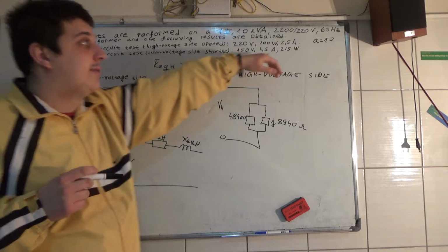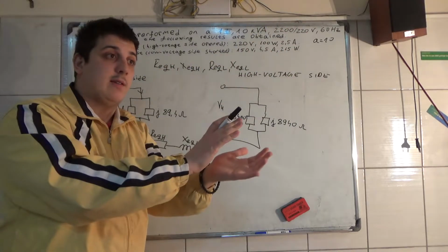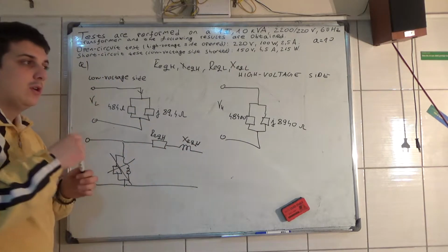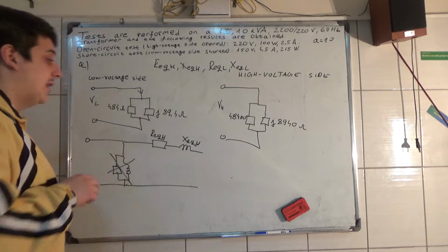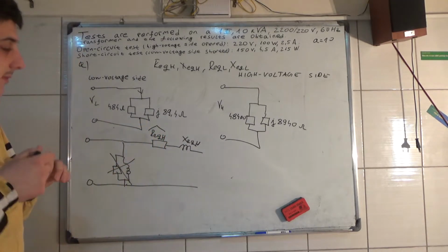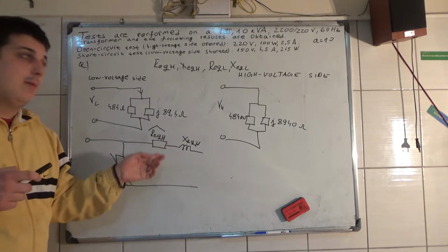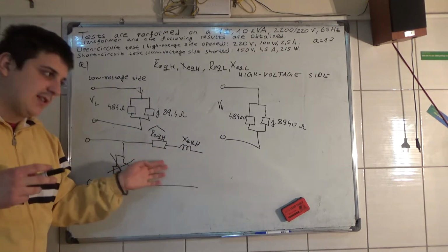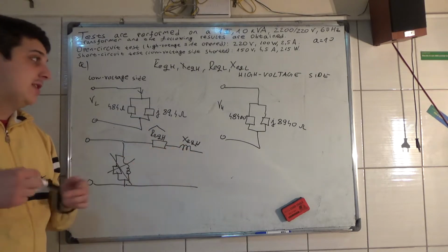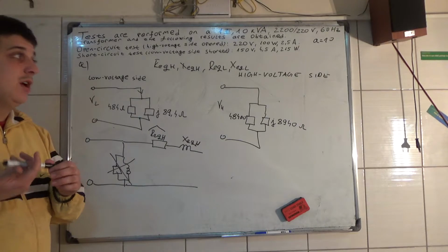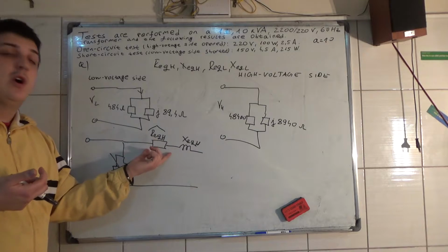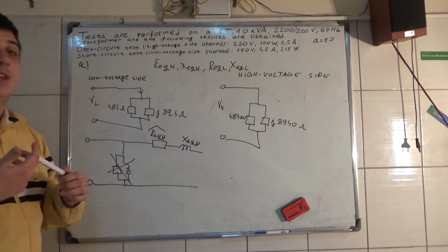Now this 215 watts goes on the active values of the circuit, and the active power loss goes on the resistive side of the transformer, and this is the reactive. Now we don't have a reactive wattmeter, we only have an active wattmeter that shows the active power, and the active power goes on the resistance of the windings in this circuit.